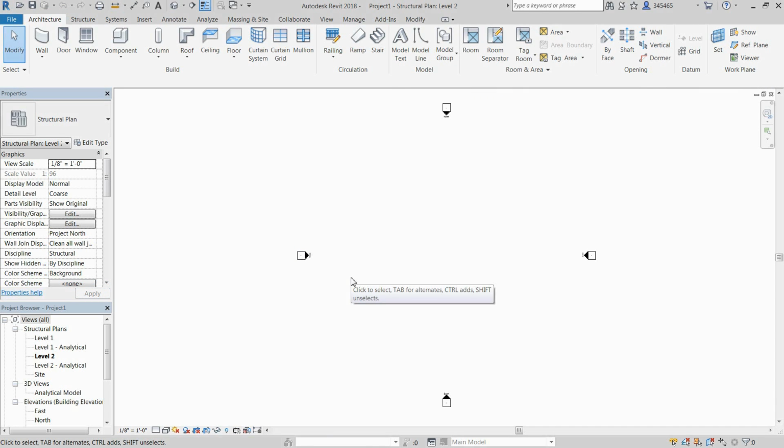coordination and collaboration. When we start a project with Revit, it's going to open with the structural template in particular to level 2. For this example, I want to go to level 1 first. That's done in the project browser. This is the default install, and on the left in the project browser I'll double click on level 1. The fundamentals of any coordination effort will begin with defining the origin.